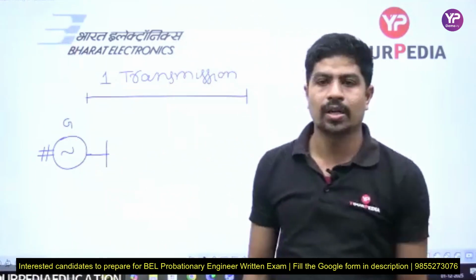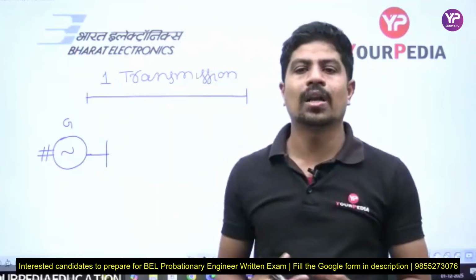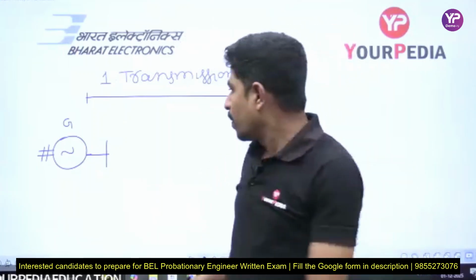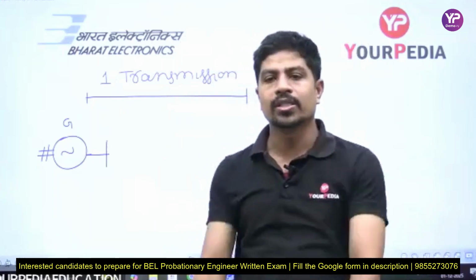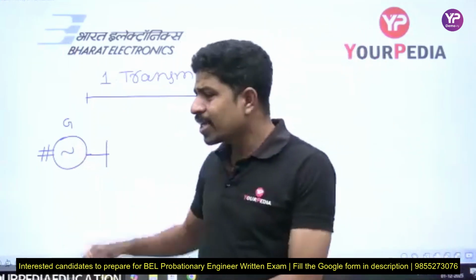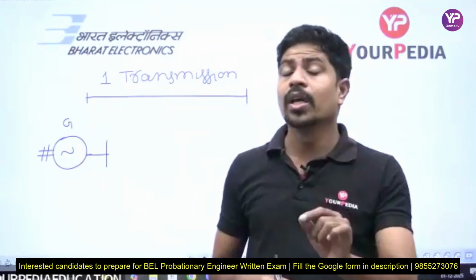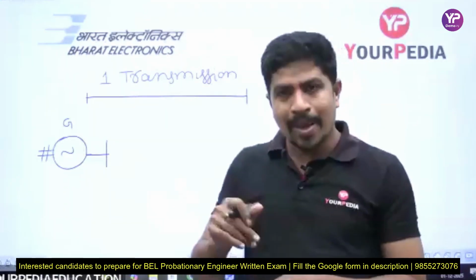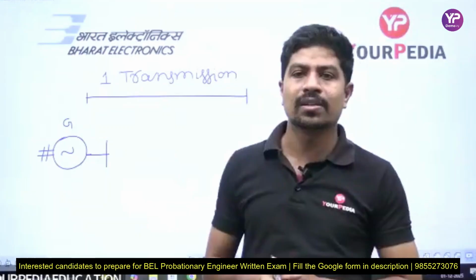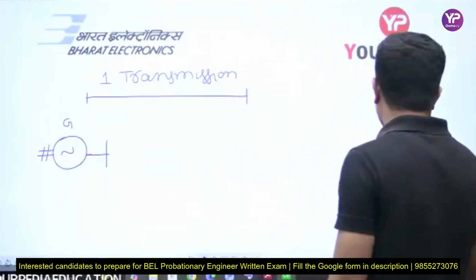It has to be transported, transmitted. Transportation is layman's language; transmission is our technical language. But we are not going to transmit as it is. We are going to step up the voltage. Generation will be done at a lower voltage compared to the transmission voltage. Don't think that lower voltage means 1 volt or 2 volts. Compared to transmission voltage levels, generation voltage levels are very low. Now we are discussing one very important thing: why are we going for higher generation voltage levels?